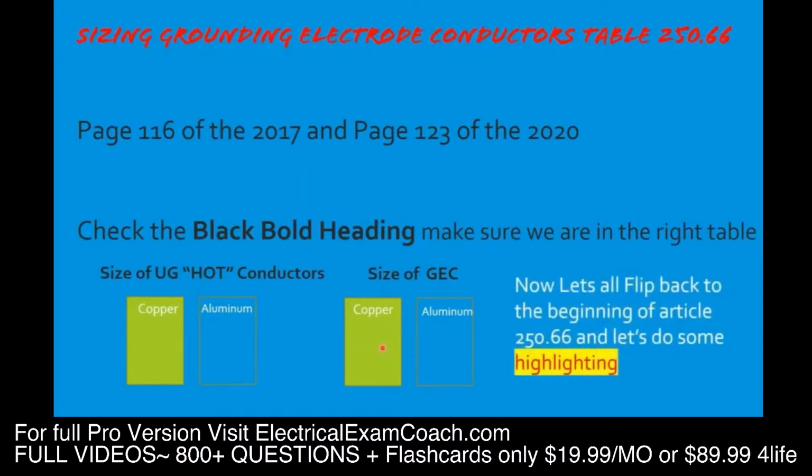Now let's all flip back one page. Flip back one page to Article 250.66. And we're going to do a little bit of highlighting. So we flip back one page, and we're going to start at the beginning of 250.66, the actual article. If you read the black bold heading, it says size of alternating current grounding electrode conductors. We're going to do some very strategic highlighting here if you're allowed to do highlighting in your state. So right underneath it at part A, I want you to highlight in the black bold heading the words rod, pipe, or plate.